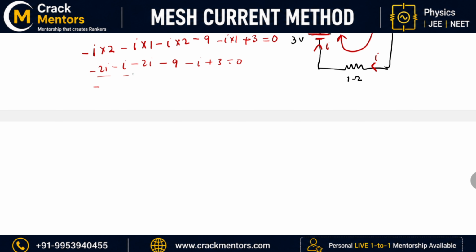Let's take this together. Minus, minus, minus, minus, all will be added. So this is equal to minus 6i plus minus 6, which is equal to 0. Therefore, 6i is equal to minus 6, so i is equal to minus 1 ampere. What does minus 1 ampere mean?